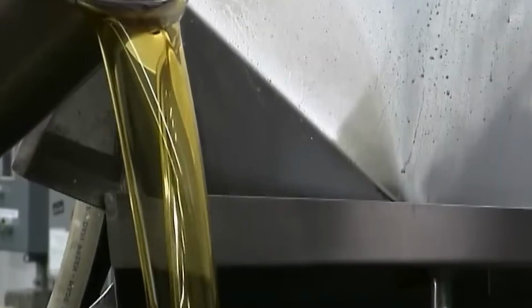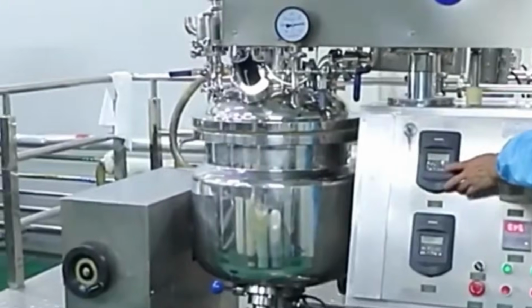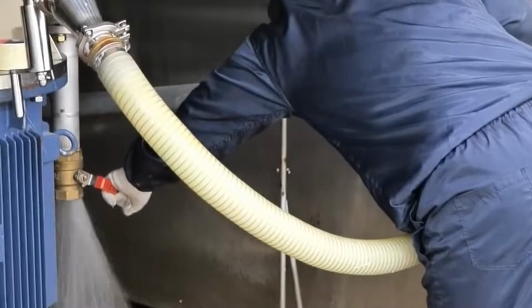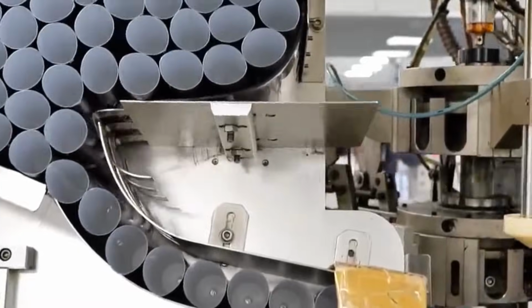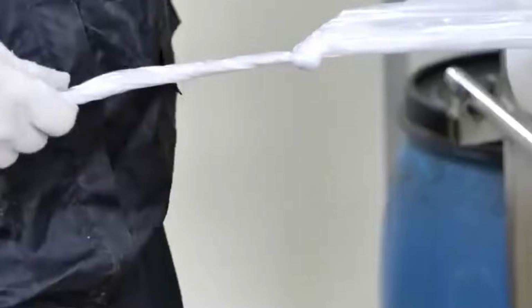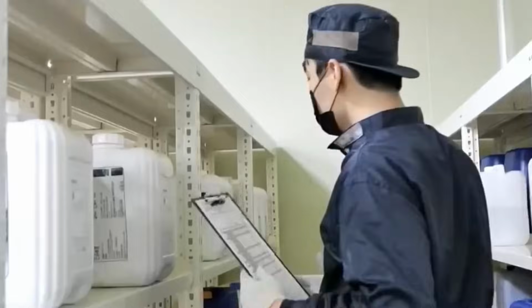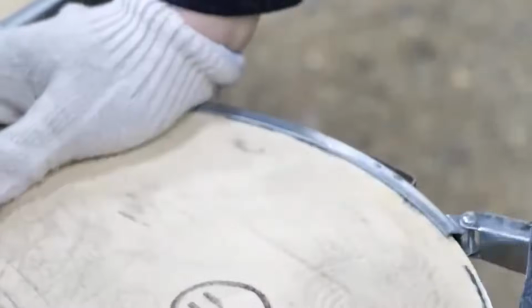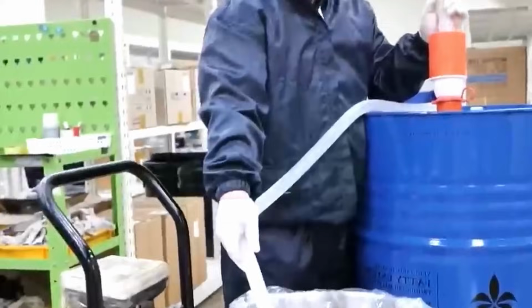A supervisory control and data acquisition system provides real-time monitoring, data logging, and batch traceability. Recipe management software stores detailed formulation parameters, allowing rapid changeover between different shampoo variants such as moisturizing, clarifying, volumizing, or color protecting types. Automated valve manifolds route ingredients to the correct vessels based on the selected recipe.